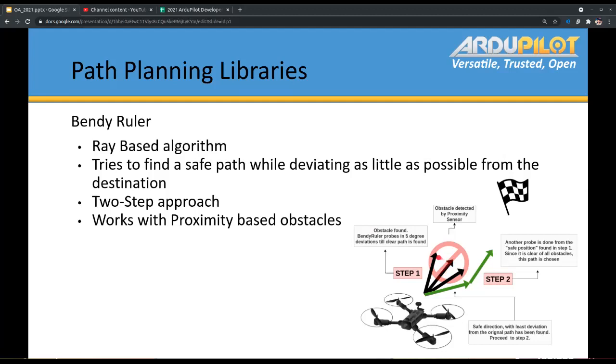So it turns 5 degrees to the left, and it sees, no, we still don't have a set margin from the obstacle. Then we turn right. It just does this ping pong of left and right location projections until it figures out a position, this green line here, that is free from the obstacle. At this point we could stop the algorithm and just go forward.